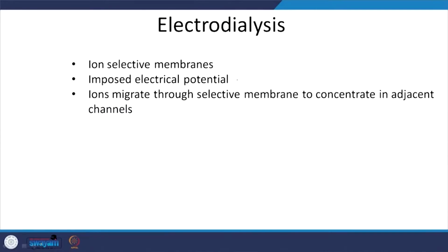So, what are the key aspects for electrodialysis? As we mentioned, we have electrodes, and then we are going to apply a voltage such that positive ions move towards one, negative ions towards the other, and then you will end up with relatively clear water that is free of charged species. But obviously, you will need to have electron neutrality.